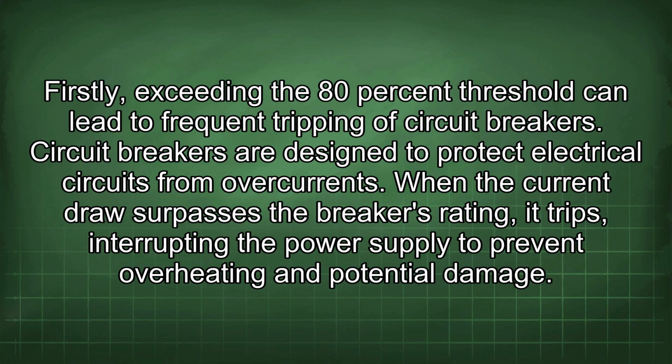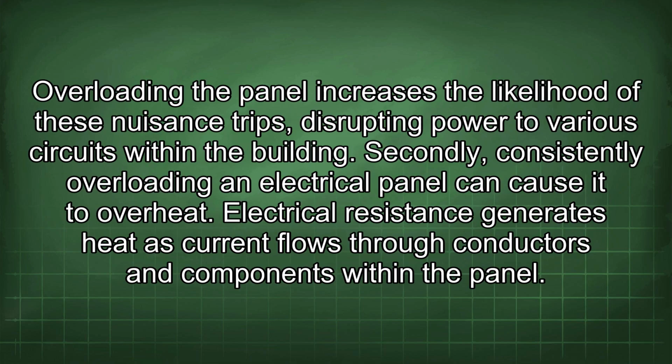Firstly, exceeding the 80% threshold can lead to frequent tripping of circuit breakers. Circuit breakers are designed to protect electrical circuits from overcurrents. When the current draw surpasses the breaker's rating, it trips, interrupting the power supply to prevent overheating and potential damage. Overloading the panel increases the likelihood of these nuisance trips, disrupting power to various circuits within the building.